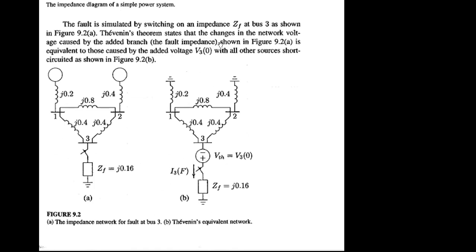So when you want to address that, if you have fault at bus 3, the bus impedance can be represented like this, right? The fault bus will have the impedance which is given already in terms of the fault path, right? So if you have a fault, what will happen? It will generate a short path between that bus and ground in terms of that fault impedance. Is it okay? Yes, sir.